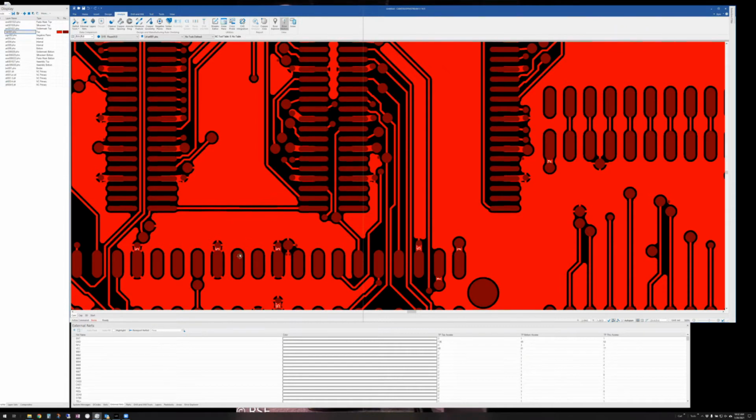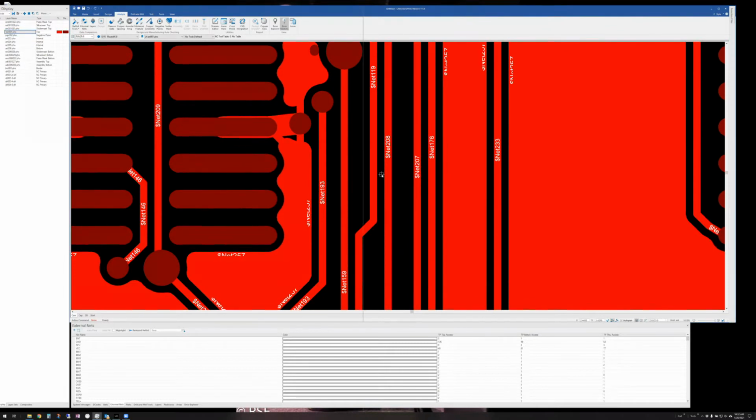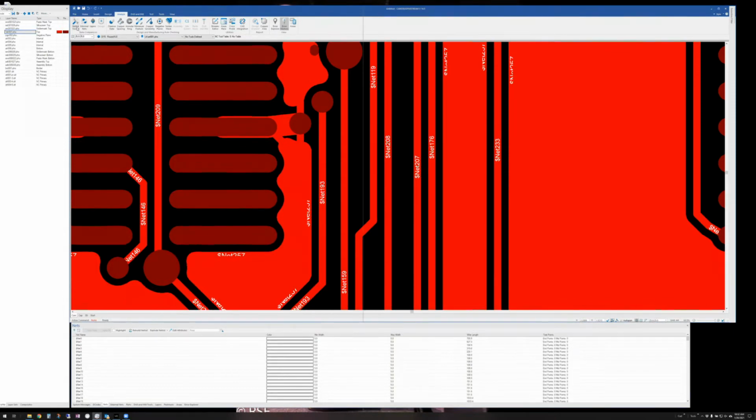All right, so I've done that, and now maybe I want to enhance the intelligence of the Gerber and NC. Since I got a good netlist compare, I can go over to Netlist Tools and tell it to override the CAM net names. It's going to pull those intelligent net names from the IPC and override the Gerber extracted net names with those. As soon as I do this, you'll see them update, and now we have something that makes sense when you're feeding back to your customer.